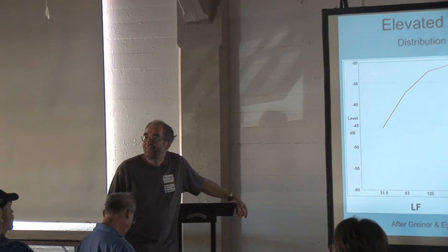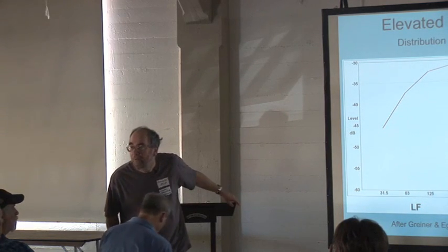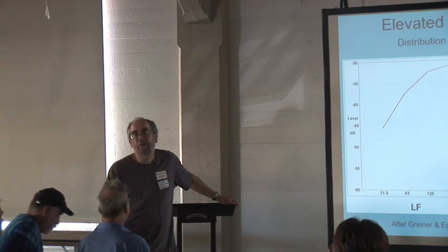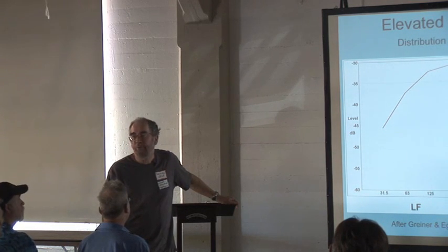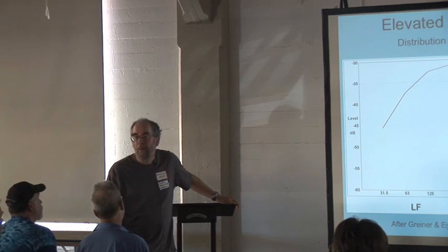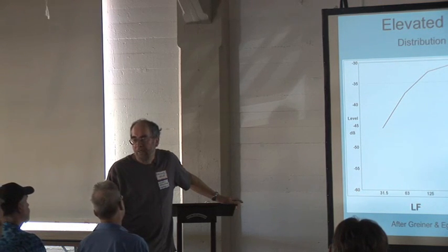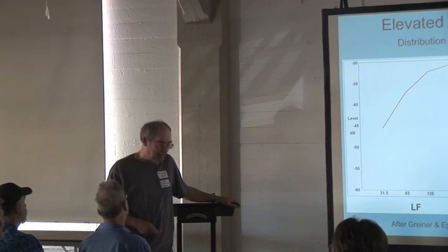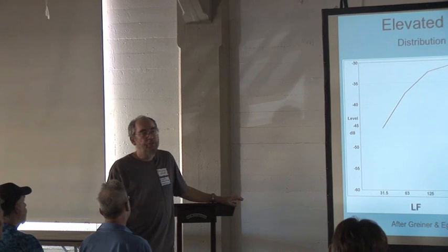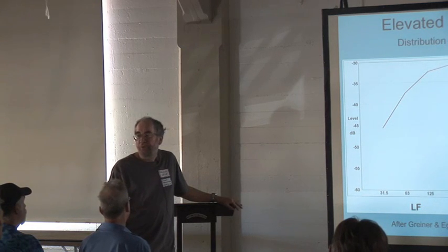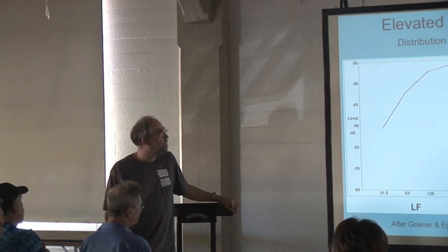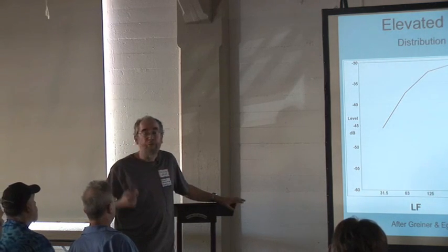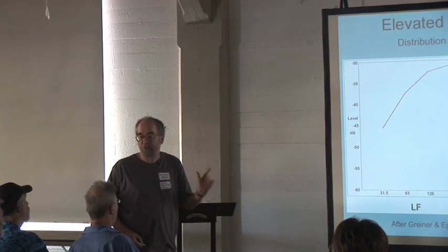What are your opinions between DSP and analog? What would your opinion of DSP versus analog crossover be? Well, I would say that, supposing you've got an analog signal to start with, then you've got to convert it to digital, do your DSP, and then convert it back. Now, I don't pretend to be completely up to date with modern converter technology. I'm probably a bit behindhand, but you're going to get some compromise on noise and distortion in doing that. I'm pretty certain that you can get a better performance by going analog all the way. If you're in digital to start with, coming off a digital source, that's a totally different question.